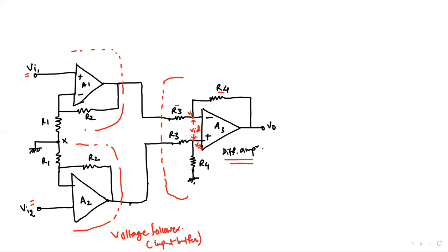There is no drop right over here. So we want the input resistance of the amplifier to be infinite, and that's why we have made this provision.